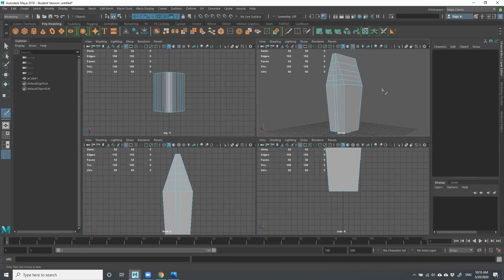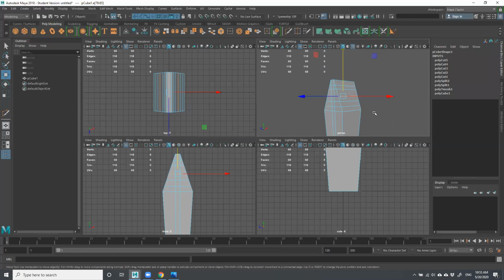And these are loops, okay? The cool thing about this, let's put one more in there, is I could take this and use a soft selection. I'm going to press B for brush, and I've just tapped B and it accesses my soft selection brush. If I hold B and drag up and down or sideways with my finger on the mouse button, it makes the soft select more or less sensitive.